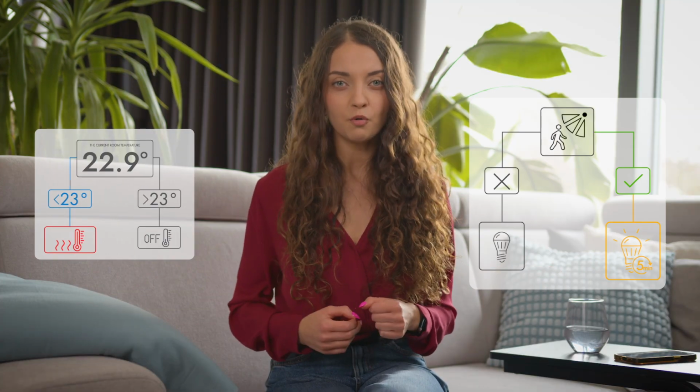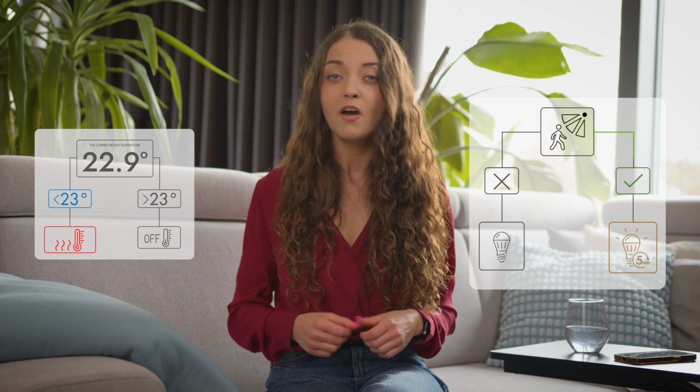Let's start with the routine. What is it? It works according to the principle: if a condition is met, perform the action. Since the Smart Hub continuously scans the readings of detectors in the system, it knows whether certain conditions are met or not. And if they are, a preset action is automatically triggered. For example, if the room temperature exceeds 23 degrees, turn off the heating. And if not, the heating should be on. Or when motion is detected in the bathroom, turn on the light for 5 minutes. No one in the bathroom? Then let the lights go out, no wasting power.